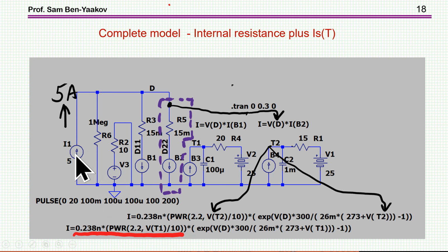So I went to a current source, which seems to be working okay. We have 5 amps, so presumably if there is a balancing between the two diodes, then it'll be half for each. Now I'm running first this model with 20 degrees centigrade per watt for one diode and then 15 degrees centigrade for the other.